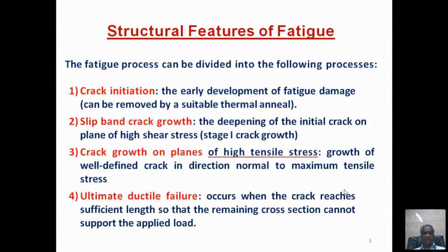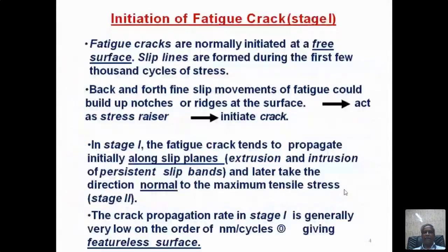We'll discuss this aspect. These are the four stages of crack, but the first stage you can remove by suitable equipment. So we'll be focusing on the slip band crack growth, crack growth on planes of high tensile stress, and the ultimate ductile failure.